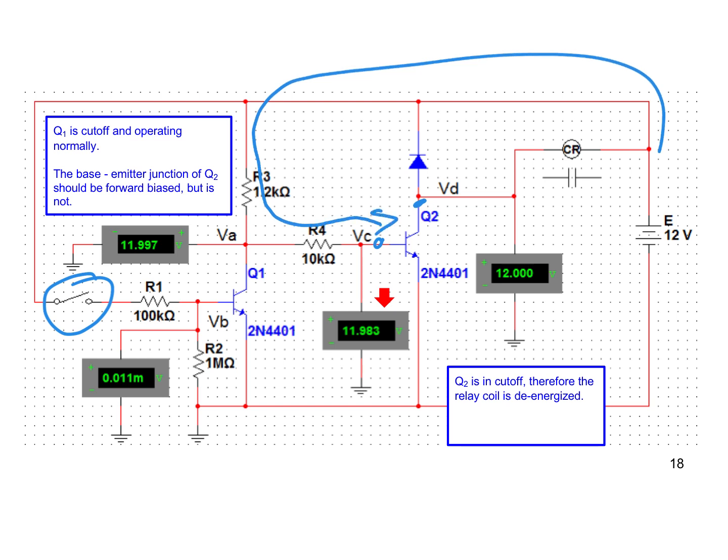We've seen that before: with that open, Q2 should be able to turn on, but in this case, because of the base to emitter open, there's no path going down through there. Hence that voltage is nearly equal to the supply voltage. So Q2 is definitely off. We know Q2 is not conducting because of that, so there's no current flowing that way.